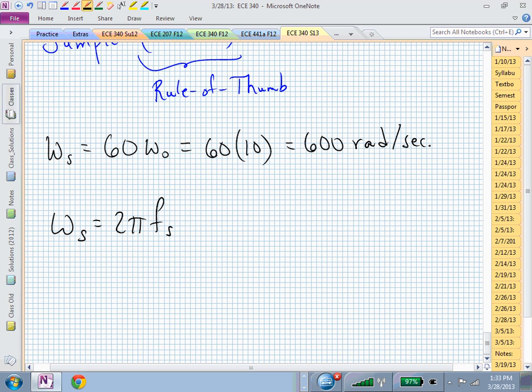Isn't it 44,000? We can hear about 20,000. Because of Nyquist, they go beyond 40,000 and they've gone up to 44,000 hertz to sample. That's for digital audio. For us, we're saying 60 times the bandwidth or 30 times. We went 60 this time. f sub s is actually probably, I would like to call that t sub s, but in the discussion I was just calling it t, so let me just call it t for now.